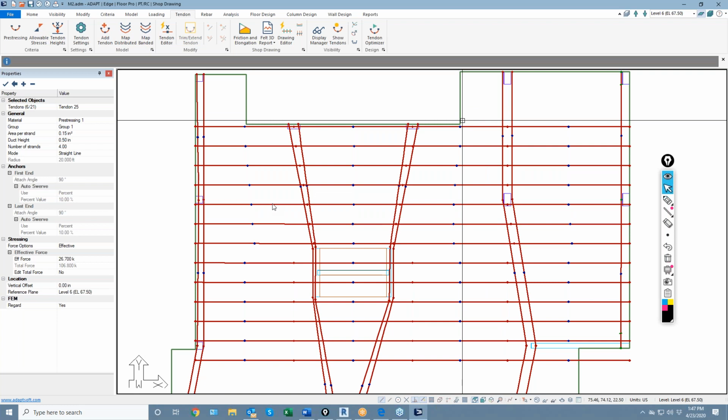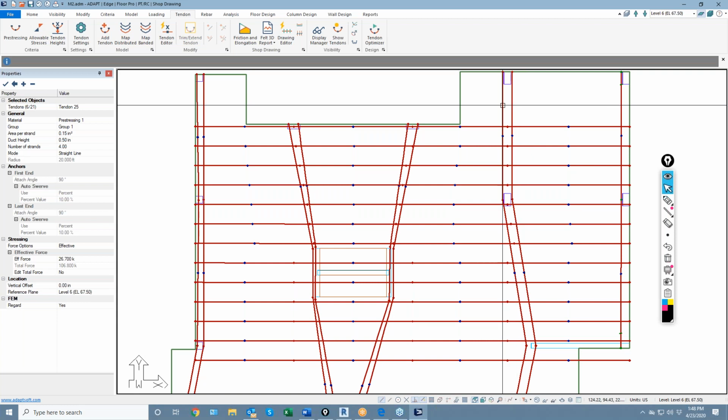Another question, why do you have only 2 strands as distributed tendons? Is it because it's an example? Usually we have about 5 tendons at 5 feet on center. It's really just dependent on the requirement. It's just part of the design. So to start, there are certain code requirements that we have for design of PT slabs. We know we need a minimum amount of pre-compression. That's the easiest thing to target when we're actually modeling post-tensioning into this type of environment.